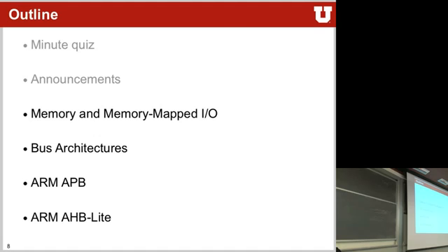The only things that you oftentimes have to change are how much RAM is there, how much ROM is there. That's about it. That's the only way that I usually touch a linker script. That's why I don't really know all the details of that particular linker script. There's so much in there. But I just copy one of them and then adapt it and change it the way that I need it to. But I can think of a case, let's say, if I'm porting some program that used to run on PCI, port it on ARM, then maybe I need to. It could be. Yes, it could be.